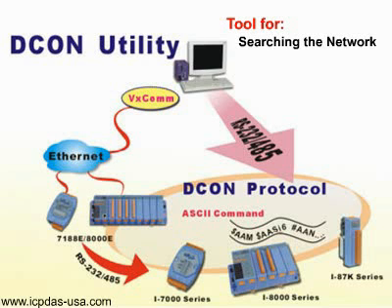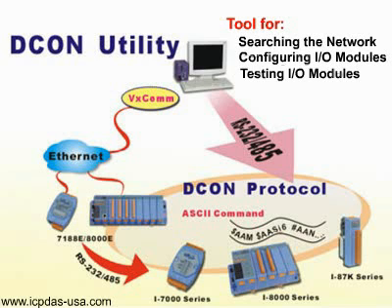DCON Utility is a tool for searching the network, configuring input and output modules via the serial port, RS-232-485, or Ethernet port using virtual COM ports. It supports not only the DCON protocol I/O modules, but also the M-series Modbus I/O modules.